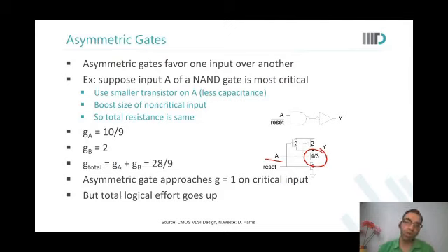And I increased the load on reset bar. Sir, how did you share the load between A and reset, sir? I reduced the load of A, so resistance of A increased. I then said, okay, let me increase the size of B so that I still get the same equivalent resistance as an inverter or a regular NAND gate.